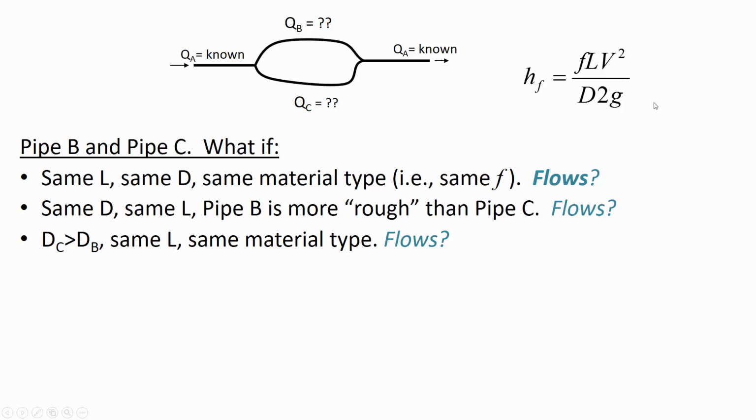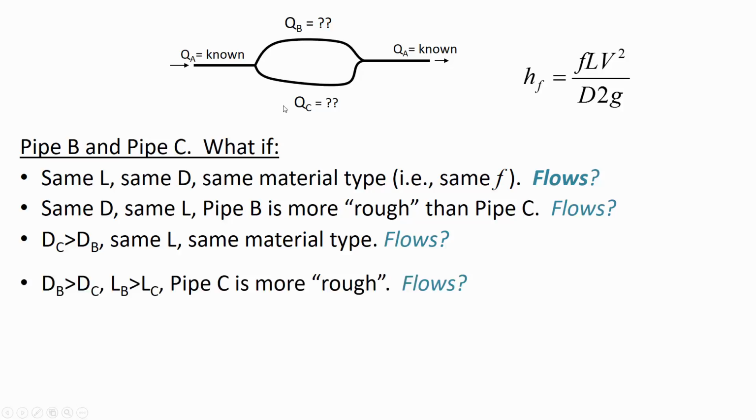If we think about it in terms of head loss, there is going to be less head loss, relatively speaking, through the pipe that has a larger diameter. So initially, if we were to change these on the fly, more water would want to go through the pipe we enlarged until it came into an equilibrium. Although there's more flow rate through pipe C, the head loss through both would be the same.